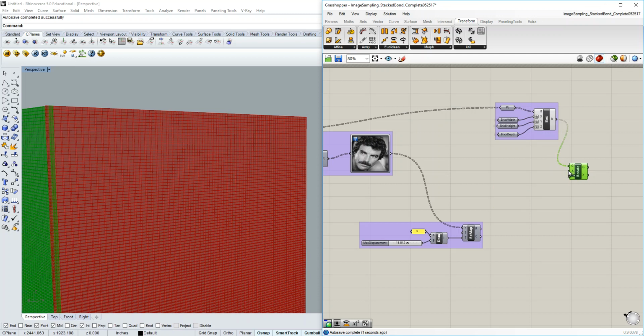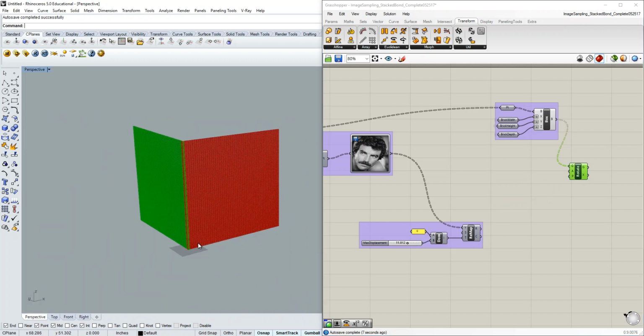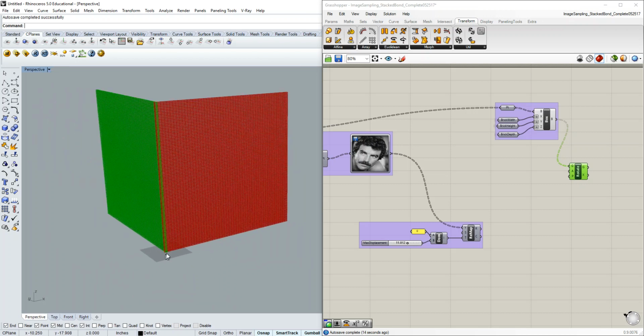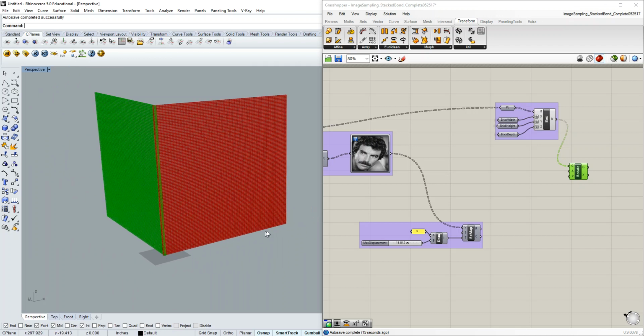We're going to skip the angle of rotation and talk about the plane. By default, that plane is set to world XY, which basically means all of the bricks are going to be rotated about the origin point, the 0, 0, 0, in the XY. You'll see what happens is the wall as a whole rotates 90 degrees. The reason is this becomes the center of rotation, so a brick that's the furthest along the X gets rotated a positive 90 degrees to the y-axis basically, and we don't want that to happen.